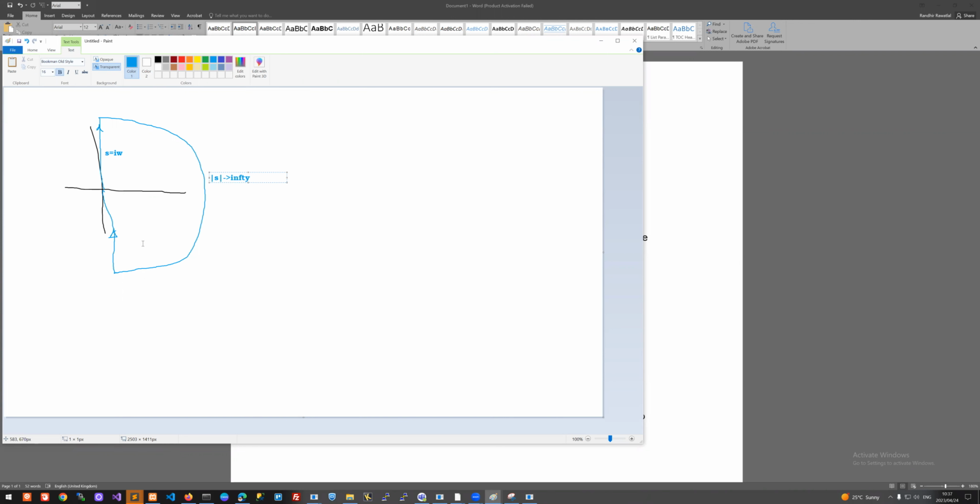So that's not going to encircle -1, 0. And then this is S equals minus I infinity. That's just going to give us the complex conjugate. G is just going to be the complex conjugate of what we have here. So there's no new information from down here. So we only have to look at S equals I omega.